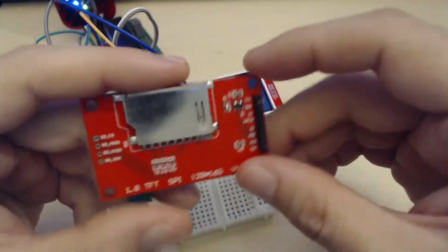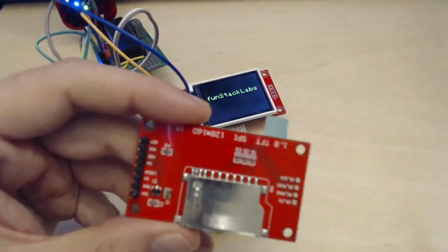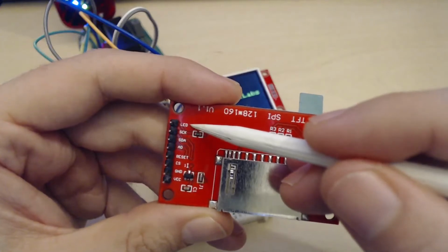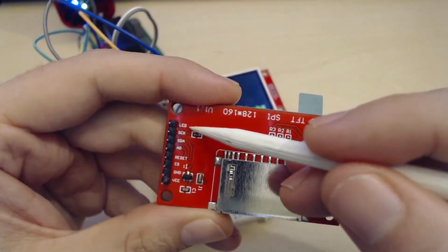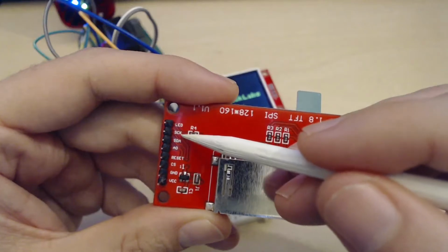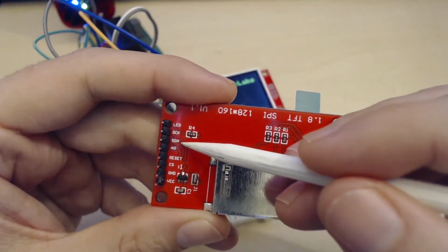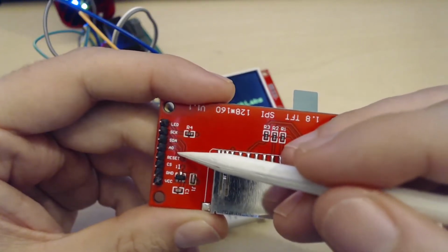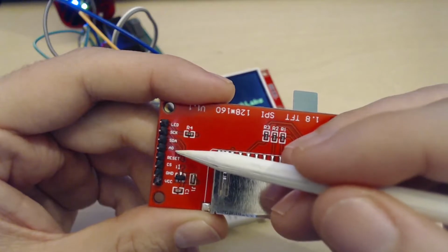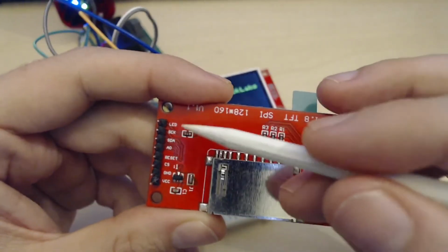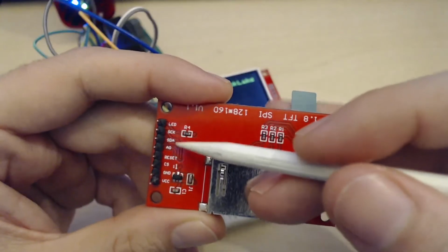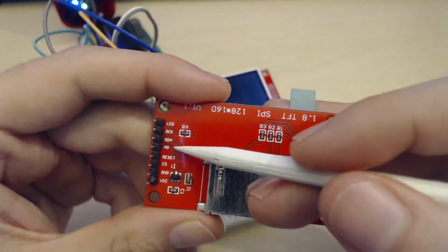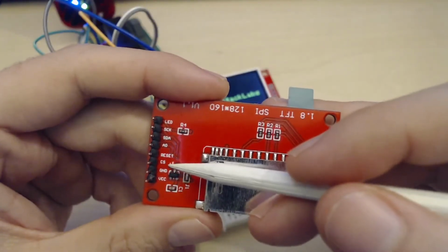Let's talk about the pins a little bit. We have this LED pin, that's for driving the backlight of the LCD screen. You have the SCK, that's the clock for the SPI signals, and SDA, that's the input and output for the SPI, so it's both connected to the same pin. A0 is for data command select. This thing is 4-wire SPI, which means you need 4 wires to get the SPI communication sorted. Clock and data are two of them. Data command select is the third one. And you also need the chip select, that's the fourth one.